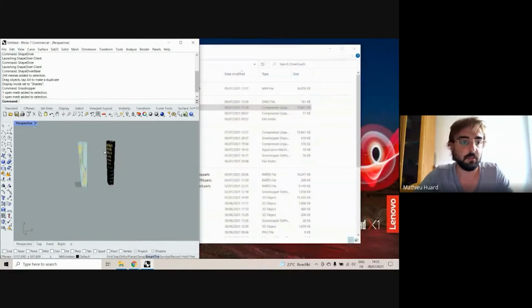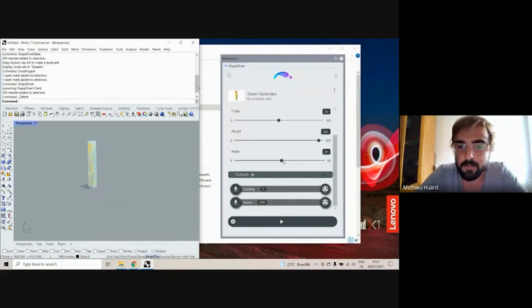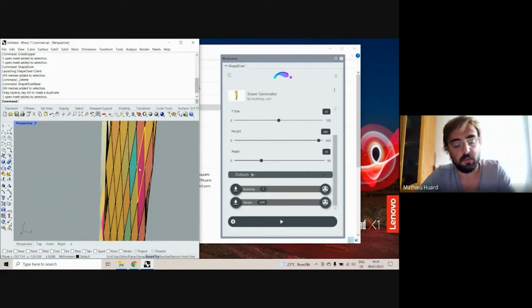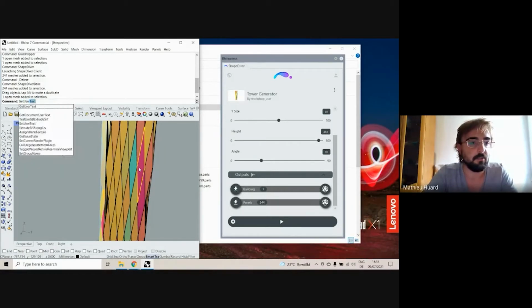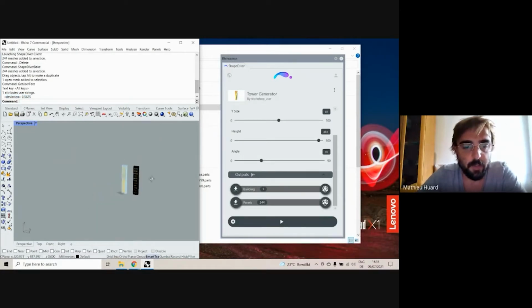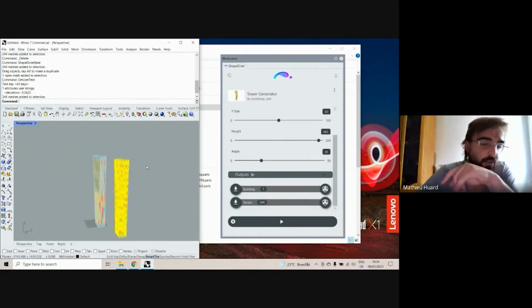So now if I close Grasshopper again and open the app, let's say I'm going to request a computation again, build the panels, and with the attributes I constructed inside Grasshopper, I can check any panel here. I can get the user text in Rhino, and I'll find one attribute called deviation with the deviation for this panel.